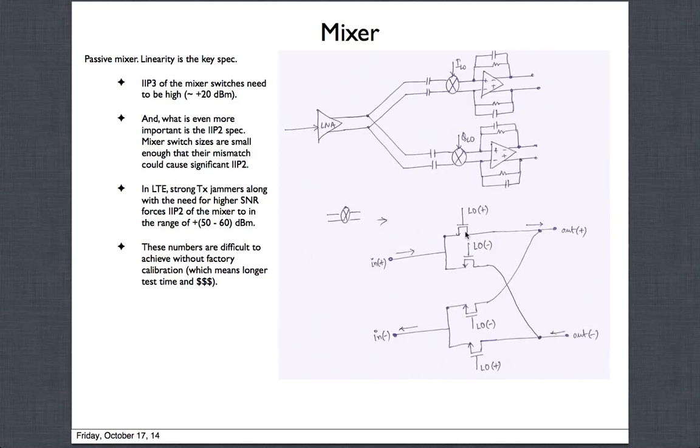With those kind of numbers, let's assume that the power is also low. There is not enough parasitic capacitance that you have to switch on and off, so power is also low, so that's also good. But what happens to the matching? If you have a width of say 10 micron and the length is 0.28, and you multiply the two, the gate area is roughly 2.8 micron square. And matching varies inversely with the square root of area. So the total area of 2.8 micron square is actually very small. That's what I'm trying to say.